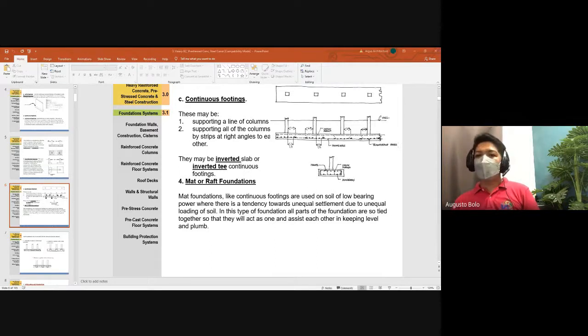But pag iba ang type of soil, that becomes bigger. Kasi, definitely, iba yung approach mo of a footing foundation. Like, pwede kang gumawa ng mat footing. Pwede kang gumawa ng pile foundation. The footing na ibang approach. Did I answer your question? But as to a regular housing like the residential, 1.2 is enough.